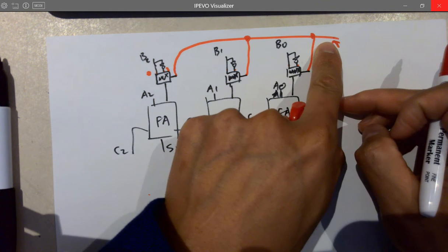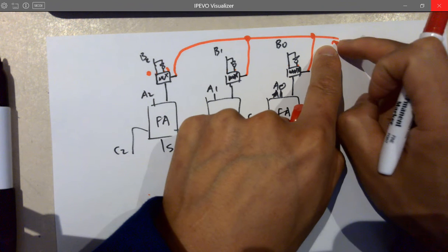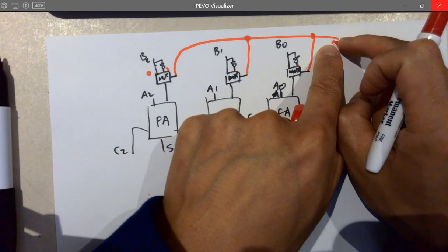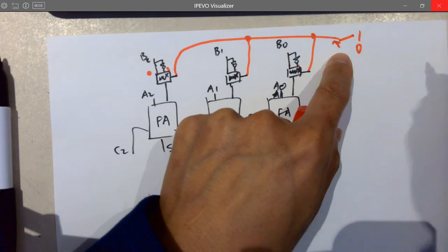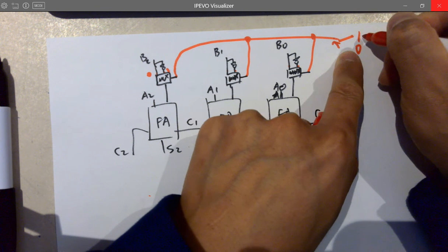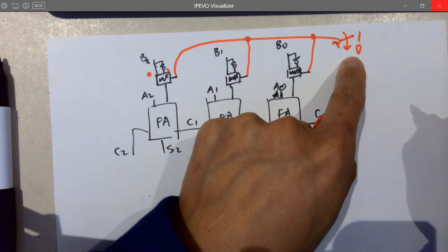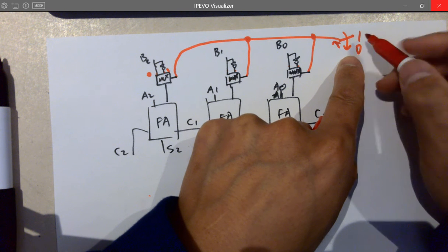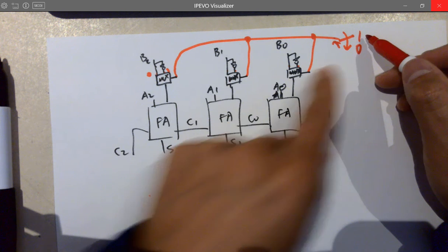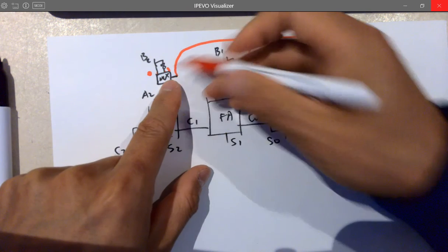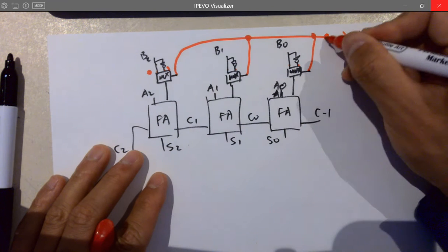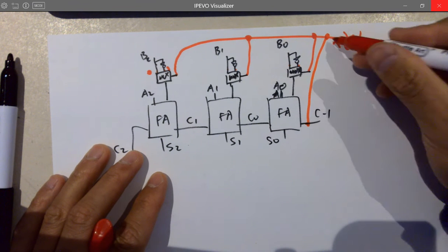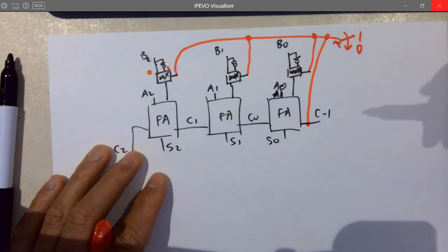So if I need a subtraction, what bit do I need for this control line? So these are switches, right? Do you want to switch it to 1 or to 0? Yes. So 1 is subtract, right? And why? Because 1 is going to select the inverted one. What else do you need for this circuit? The carry. Whenever it's 1, you invert it and then plus 1, so you can get it done.